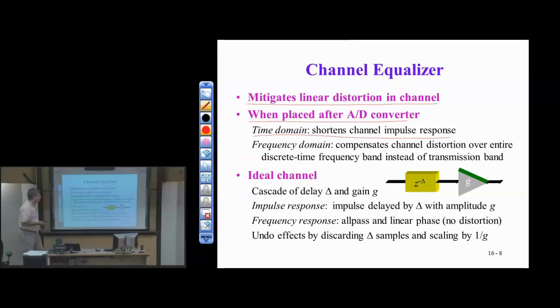The second impact that the linear time invariant part of the channel has is that there's a frequency distortion. That impulse response also reflects in the frequency domain, in that I'm going to alter the magnitude and phase of the transmitted waveform as it goes through the channel. Now, more than that, those are LTI effects, or linear time invariant effects. In practice, that channel is going to vary a little bit with time due to simple propagation of the waveform in the media.